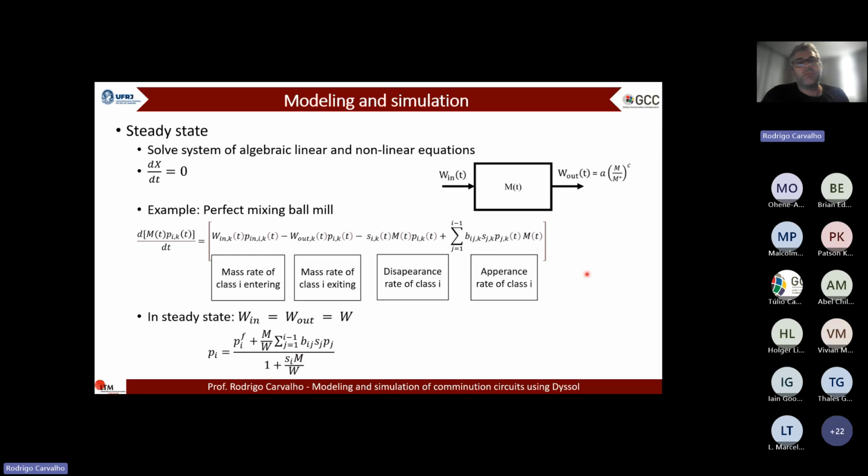And the thing is, when you are organizing flow sheets in order to perform a dynamic simulation, for some units in the comminution circuits, you can assume that they will give an instant response. You may say that it varies with time only because the inputs to a steady state equation are changing. So basically, we have an instant response of that machine. This can usually be considered true when we simulate fast machines when compared to others. For instance, in a mill, you can have residence times as high as half an hour or even more, while in crushers, the material takes just a few seconds to pass through.